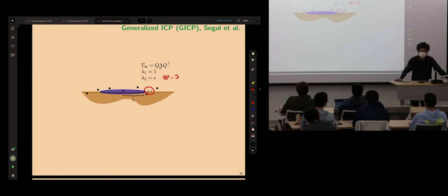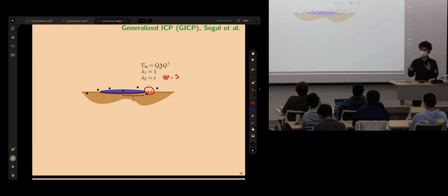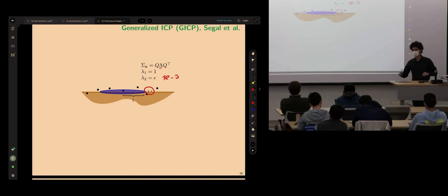That depends on many things, including how much time you have for calculations. You don't want to go too far because then that will make the covariance too large. It's supposed to be a neighborhood, but if the point cloud density is not high enough, that makes it very challenging because the neighbors are far, and that creates a covariance for a large region that's not reliable. I'm saying a reasonable density, but something that when visually you look at it, it describes the shape of the environment. Maybe 16, 20, 24, something like that might be a good choice.